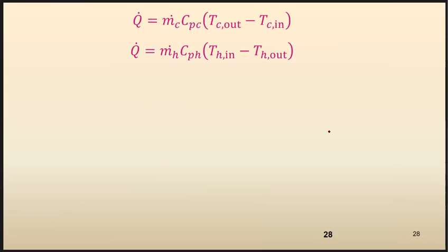Because instead of calculating heat transfer rate using these two separate equations that are also equal, ideally, you want to use one single equation. Overall heat transfer coefficient times the area through which heat transfer is happening. And that area depends on the structure of your heat exchanger. If it's cylindrical shape, is it flat plate?